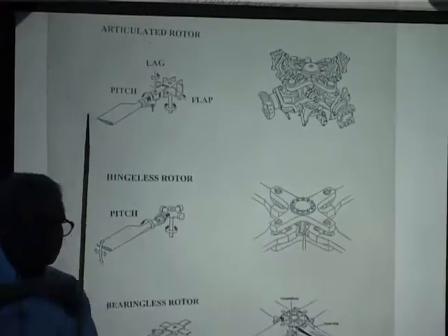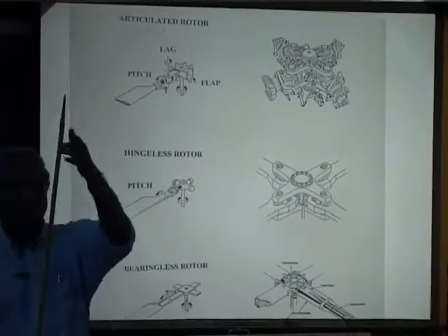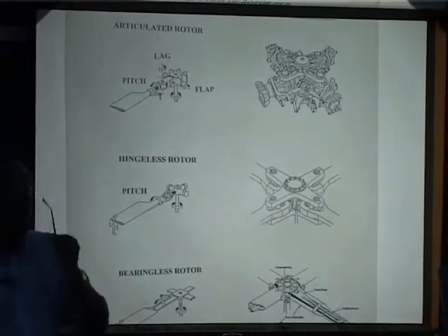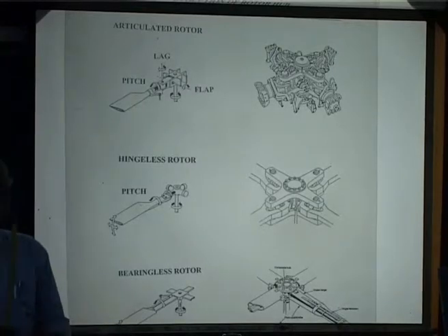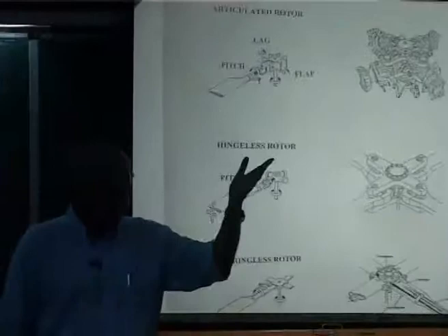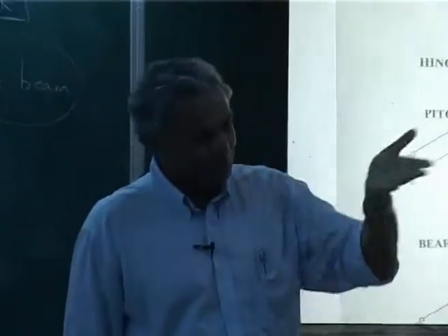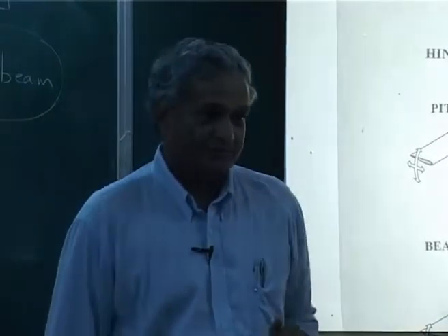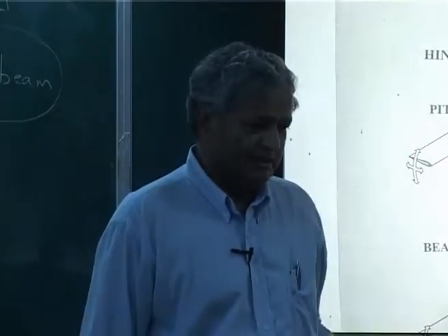The pitching moment comes as an axial load on that member. Now you can make it very bulky, heavy, so that you will give infinite life, but they don't want infinite life. So what you do is you reduce the weight, but life also goes down. You say so many hours, after that remove it.